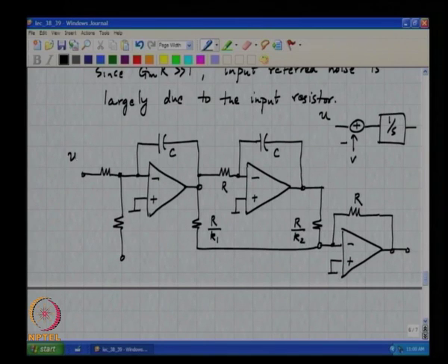For instance, this is U and this is minus V, and you need to have, I am sorry, you need an inversion. So, all right, and once you close the loop around the quantizer, the signs must be chosen so that there is overall negative feedback. Okay, you must carefully follow through the inversions and so on.